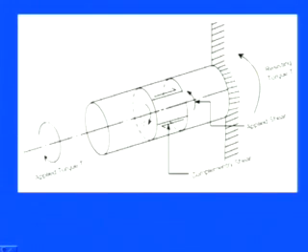So what we are doing here, we are simply taking a small section of this particular bar, and after observing that phenomenon, we found that the elements lying along the center line have less tendency to move, but as we move from the center outward, on the circumference, the tendency to move in the direction where the torque is applied is greater. That means the effect of the torque is more on the circumferential side.